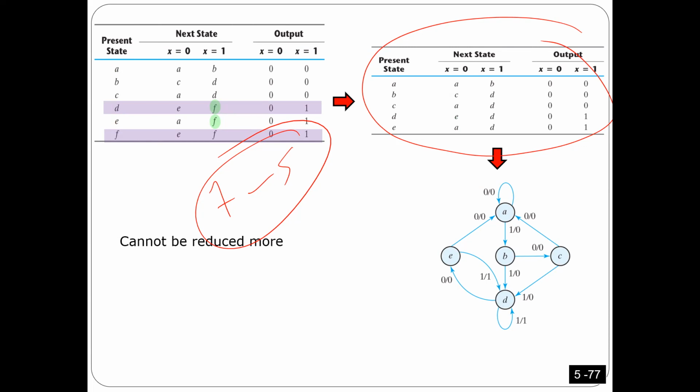You understand what I'm saying? Less hardware. So the question now: by doing that, do you guarantee that you are going to reduce the hardware? The answer is sometimes yes, sometimes no. It's not guaranteed. Why? I'm going to tell you why. Simply because if I have n flip-flops, that means I can have up to 2 to the power of n states. So for example, in this case, if you have 2 flip-flops, you can have up to 2 to the power of 2, which is 4 states.